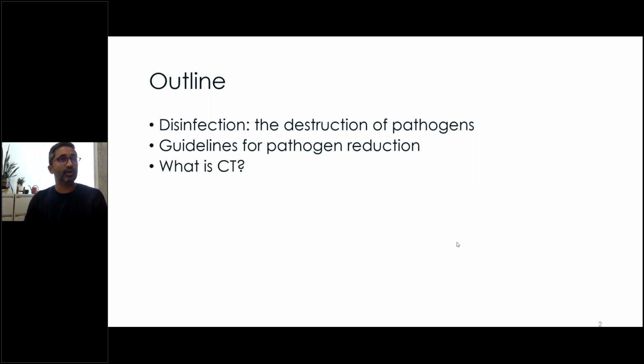And then one thing we'll notice is if you look at the drinking water guidelines, they're often referring to a particular CT that you need to achieve and the corresponding log removal that comes from achieving a certain CT for a different pathogen. So that brings up the question, well, what is CT? If I look at those guidelines and it's giving me numbers for CT, what does that mean? What is that CT? So we'll talk about that, introduce the concept of CT.